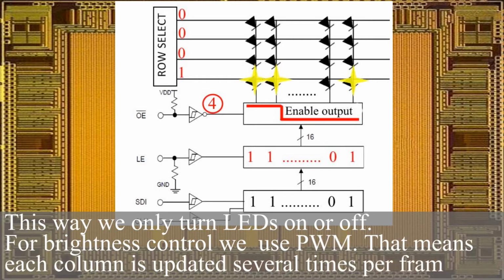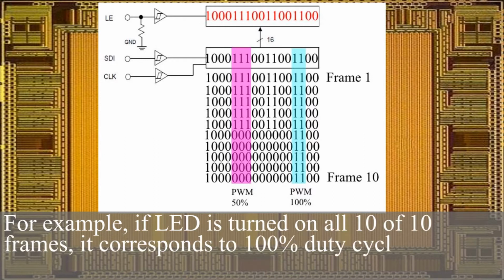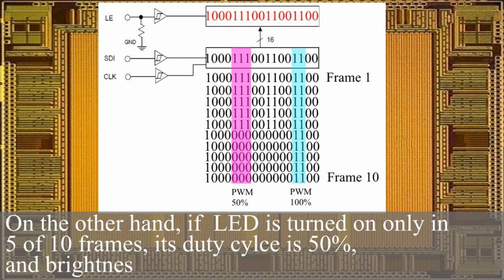For brightness control we use PWM. That means each column is updated several times per frame. For example, if an LED is turned on 10 of 10 frames, it corresponds to a 100% duty cycle. On the other hand, if an LED is turned on only in 5 of 10 frames, its duty cycle is 50% and brightness is lower.